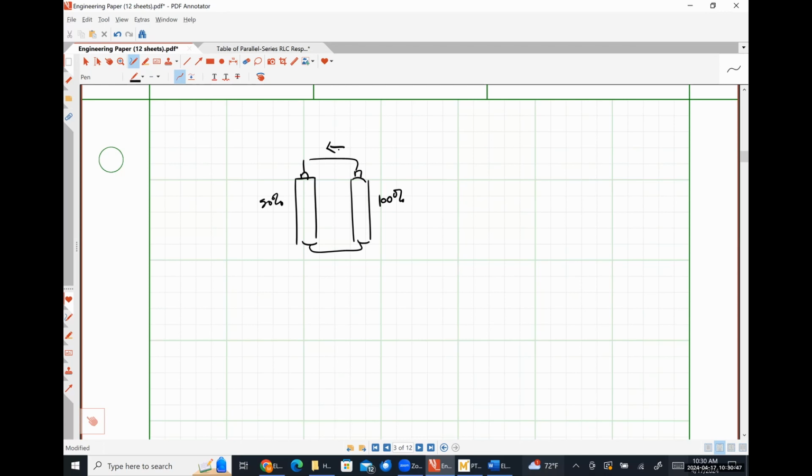Yeah, so effectively, if you apply a certain amount of magnetic field, you'll line up all the dipole moments, but it can only get so good, and that's where you start to hit saturation in your hysteresis curve. When you're coming back down the hysteresis curve, let's say you turned off the external magnetic field, there is residual magnetization. So that material effectively has some amount of memory because it's stored what its dipole moments are looking like at that instant of time, even with no external energy applied to it. It takes a certain amount of field in the opposite direction to demagnetize that material, and then the loop changes.